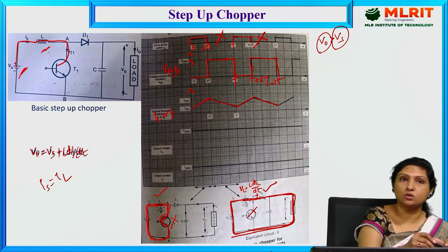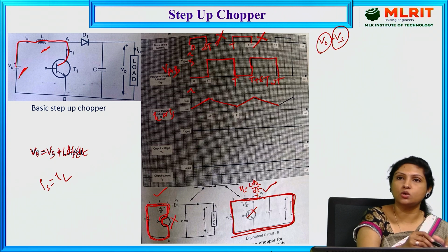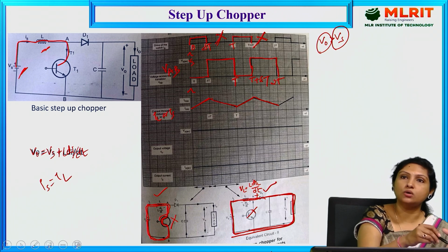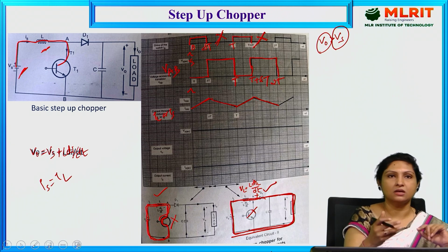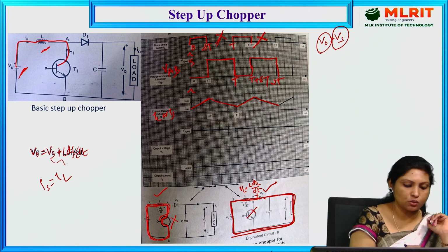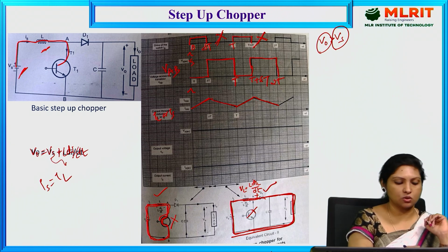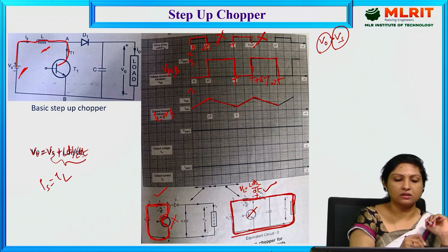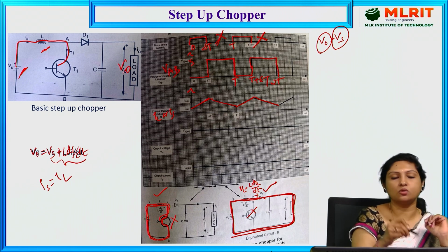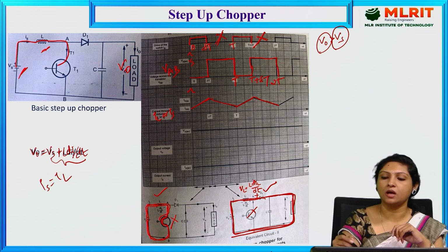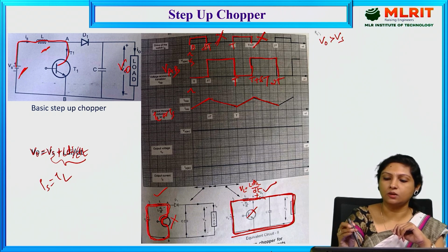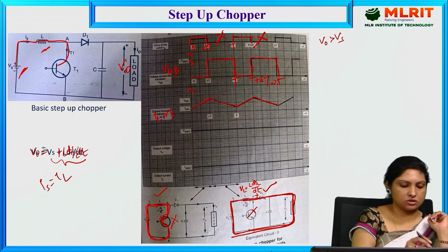The voltage across the inductor is adding on to the supply voltage which we are actually feeding. So that is the reason the summation of the supply voltage as well as the voltage across the inductor is nothing but the net output voltage which we are actually getting. So that is how we are obtaining an output voltage greater when compared to the supply voltage.